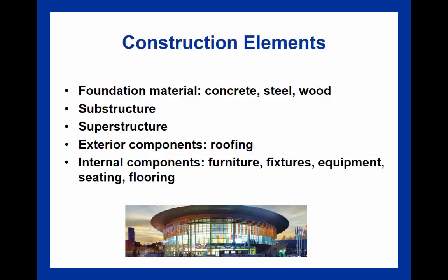Once we go through that, we might need to go through the site preparation of this facility. That is where the field office is going to be established. Maybe access roads that didn't previously exist need to be created, along with clearing, and removing shrubs and vegetation. There might be some grubbing, which is removing some of the excess vegetation, and that is usually paired with boring into the soil, which we discussed in the last chapter, to make sure that soil is suitable for the proposed foundation of that facility.